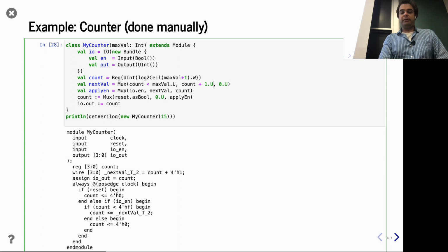In terms of the other parts of the design, we could then, of course, have our enable signal. In this case, I'm doing it very manually rather than using something like the reg enable. I'm just doing reg. To manually construct the effective enable, we are either taking an X value or the count, meaning we're not changing, and then putting everything together, right? So either we're resetting or this one.